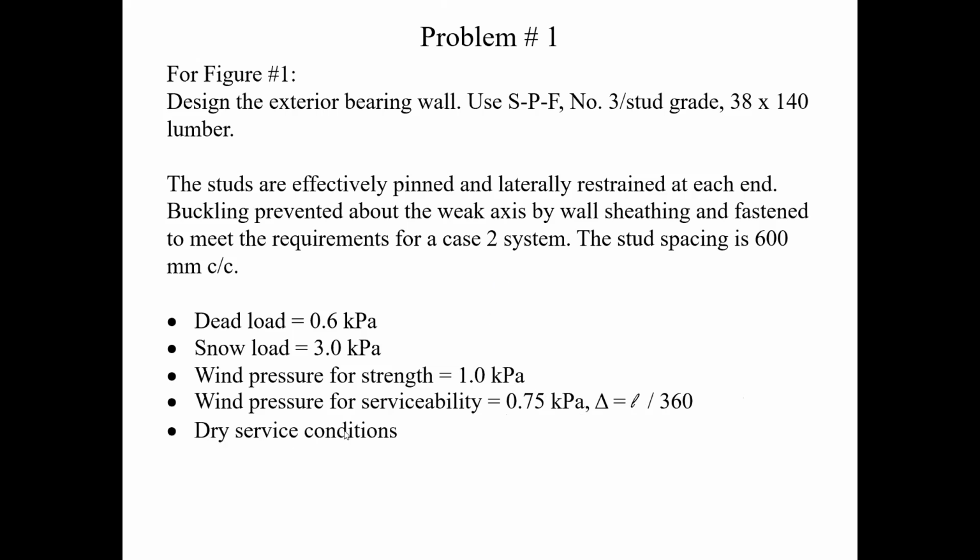And of course, we have dry surface conditions. It's going to be a wall. It's going to be untreated. And of course, the studs are concentrically loaded because the truss goes right over the wall. You can assume that the stud is concentrically loaded, and therefore you don't have to worry about that other column where you have the eccentricity.